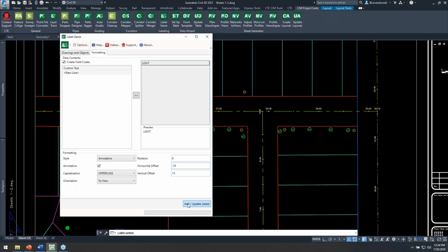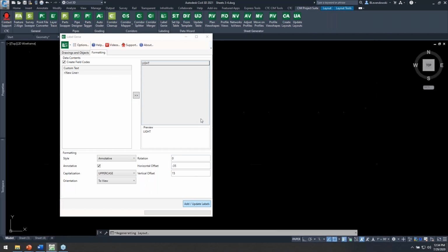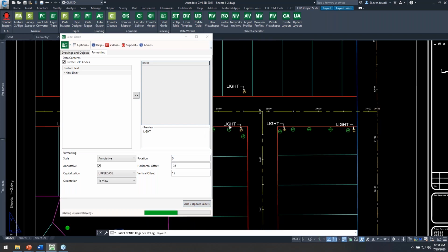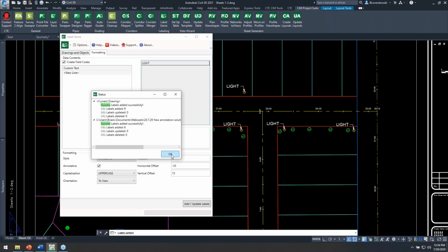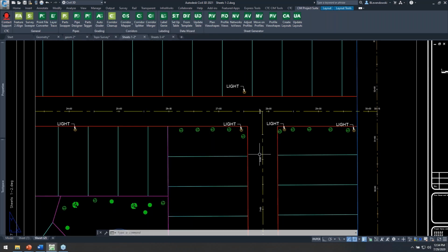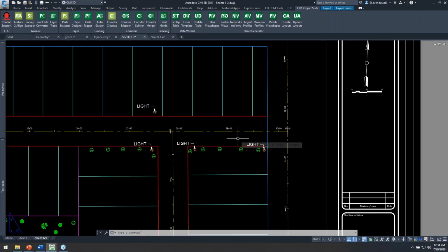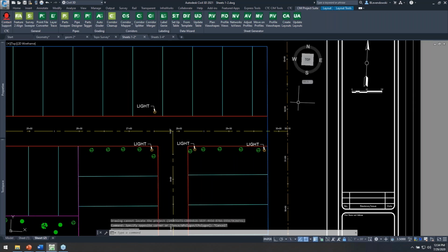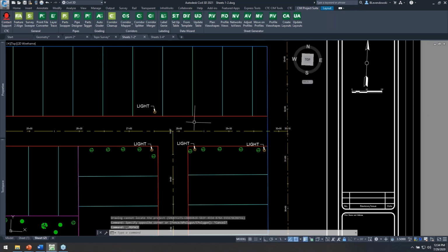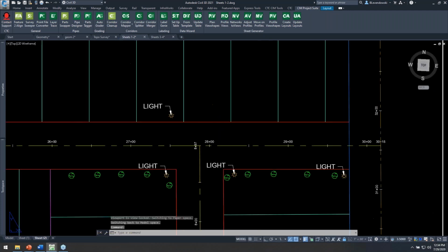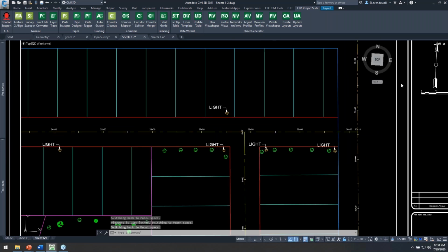And we'll hit add labels to this. And we should see a bunch of Mleaders come in. Okay, and you can see it labeling all these different blocks in there. Now notice my north arrow over here, okay? There's actually a twist or a rotation to this viewport. Because I selected orientate to view, it's not, right? It's not rotating the world coordinate system. It's actually aware of the viewport orientation, and it'll insert it accordingly.